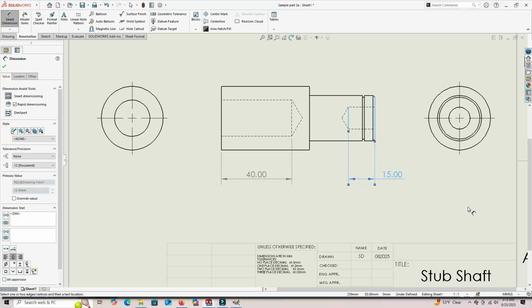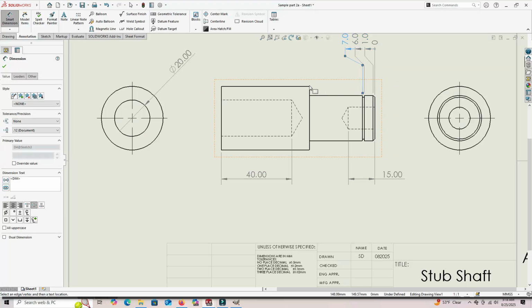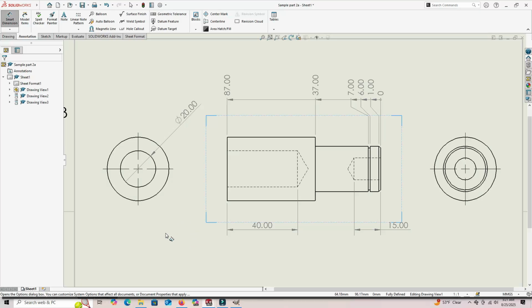Ignore the purple box, that'll disappear, and obviously that is what you would see. I'm going to add maybe the diameter of that hole, and how's about just, I did ordinate dimensions before, so let me do that real fast. Clicking my points, drag it up there, and then I can just click all the points in between. There we go. That should be plenty of dimensions to show what I need to show you now, which is how to change the number of significant digits.